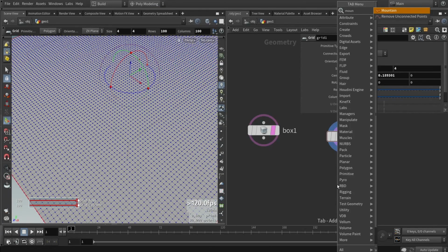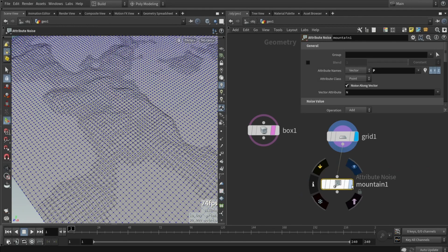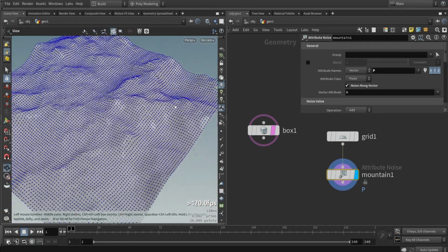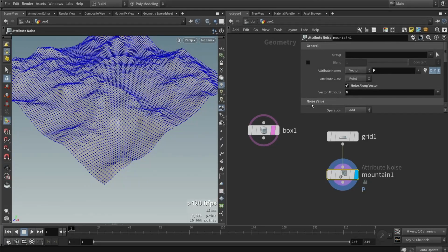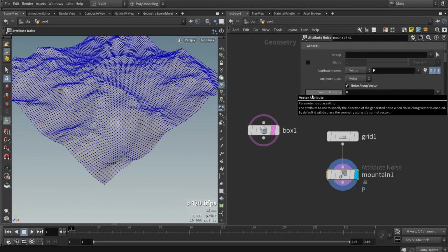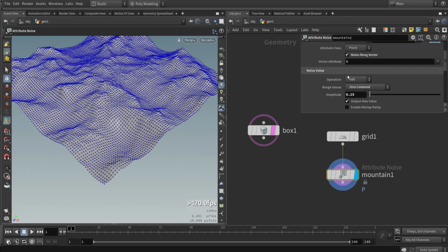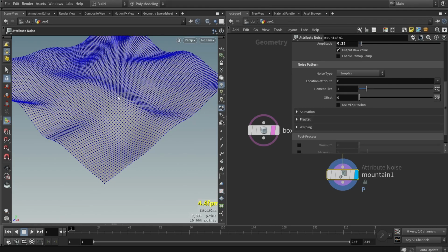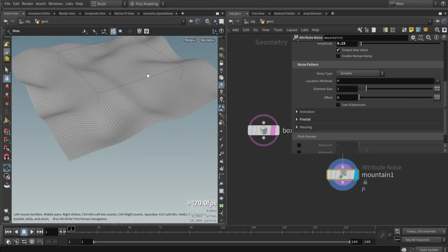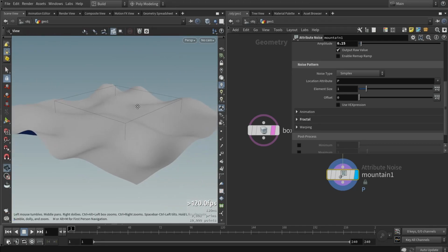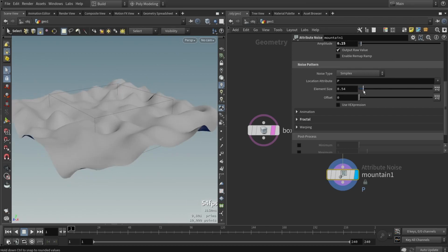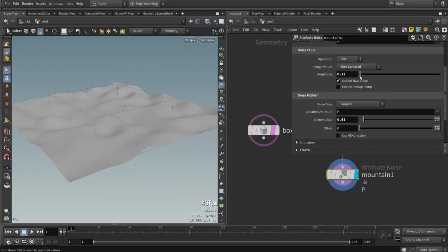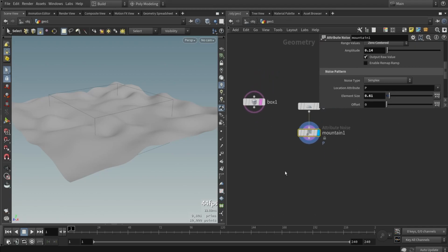So if we now would do a noising pass with a mountain noise, we can see that we can now add these roughnesses here. What I will usually do, I mean, fluid is not usually that fine in roughness. So what I will do here is I will go to a fractal and disable the fractal type. So you can see that we'll make it less noisy. So we'll have something like a smooth plane like this. We can maybe tweak the size here a little bit. Maybe we can fine tune the intensity, something like this. You can of course go back and forward.